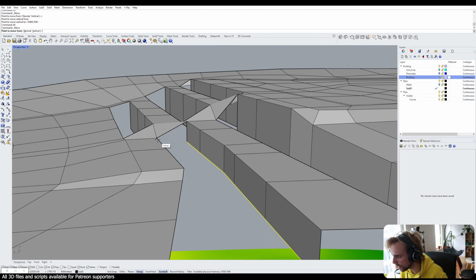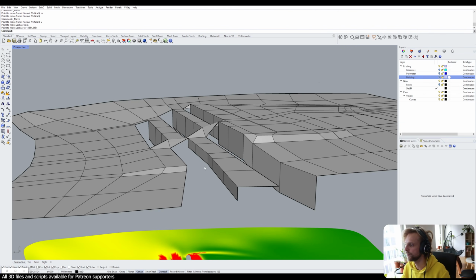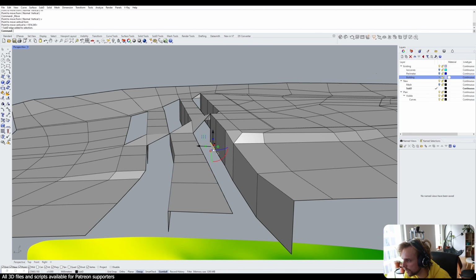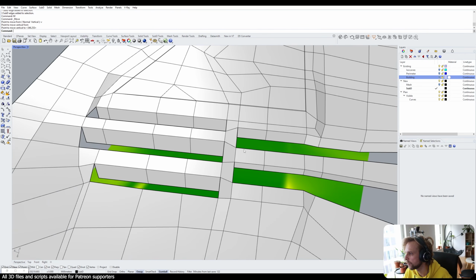And I think that I want to fit it with this point right here. So I'm going to try it again, move vertical from here to here. So M, enter, V, enter is a very, very strong tool to use. Keep that in mind. Like that. Perfect.